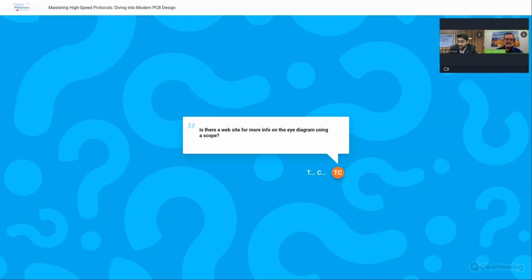Yep. Right. So we have another question from Tony. Do you need a moat around a ground plane under a high-speed signal? Normally, no. If you control your layout with placement, and this is in one of those skipped elements of the presentation on Microchip U, there's a whole little section that talks about how to manage the layout so that you isolate circuits with placement, physically isolate them so that you don't have to have crossings. Then usually you do not want to put moats on any board.